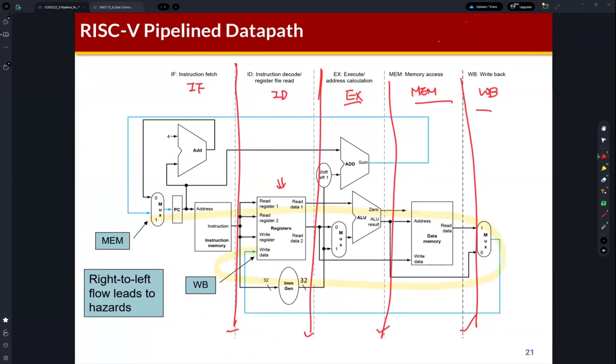So this is the single cycle processor, and I mentioned that this yellow line is the critical path. We want to reduce the critical path of this design. Then we can just cut this combinational logic path, and we can insert what? D flip-flop.